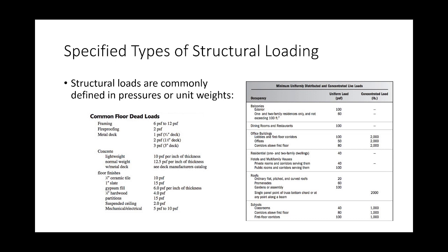If I'm designing this building, how do I design this floor beam? I need loads. I need force per foot. I need all of that stuff. Where does it come from? Well, it typically comes from what the structure is being used for. We have different loads that we apply to bridges than we do to buildings. We have different loads that we apply to simulate different types of load events, like dead load, like live load, like snow, like wind, like earthquakes.